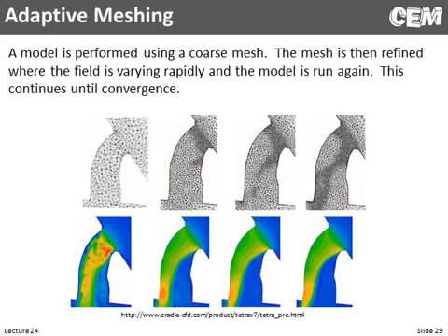There is also something called adaptive meshing. And what you would normally do is you'd start off with a very coarse mesh, and you would do a simulation. And you would see certain regions where whatever function you're finding, maybe it's an electric field, in this case it looks more like a temperature profile or stress or strain. You look at where that unknown function is varying very abruptly, and you say, I probably didn't resolve that with enough elements.